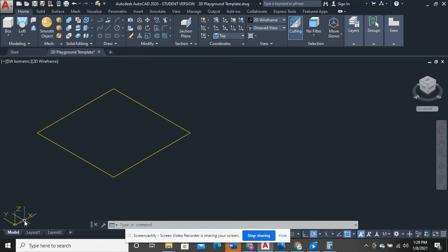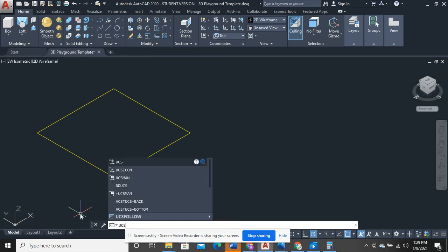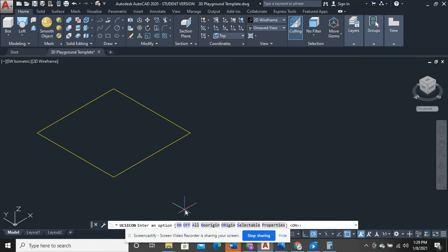So if that's the case, if you start putting a tower and a slide and all those things here, and you want to anchor this UCS icon, you type in the word UCS, and you'll see the second hit on the pop-up menu is UCS icon. If you click right here, or you just hit letter N, spacebar, or click no origin, it will fly that UCS on your screen. Mine was already docked, but it'll fly it down here, and that's going to keep it anchored in the bottom left, and that's helpful to me.